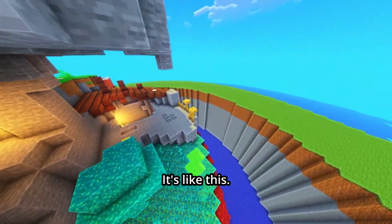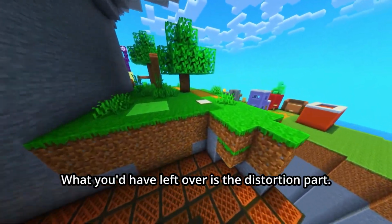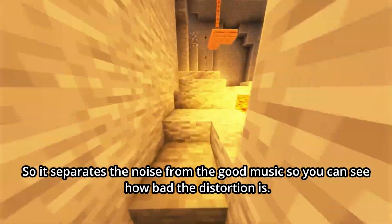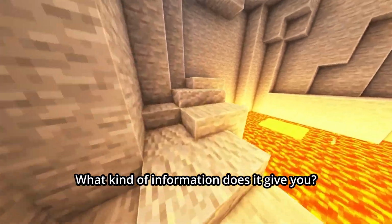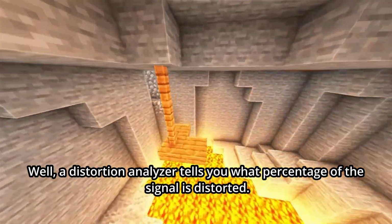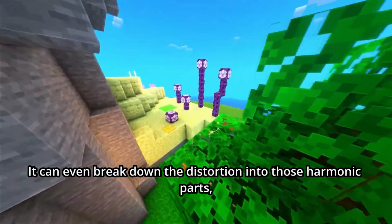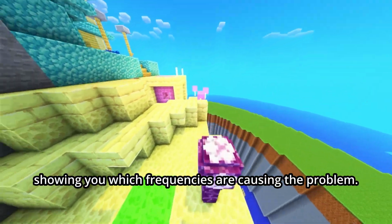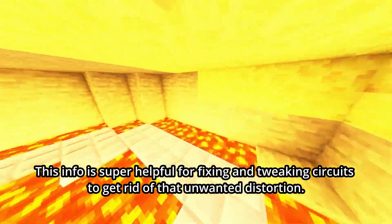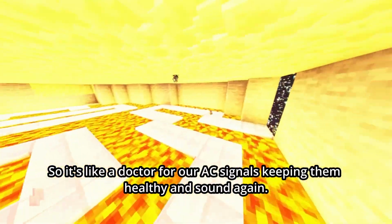It's like this. Imagine you could filter out the perfect main frequency of an AC signal. What you'd have left over is the distortion part. So it separates the noise from the good music so you can see how bad the distortion is. What kind of information does it give you? Well, a distortion analyzer tells you what percentage of the signal is distorted, so you know how pure it is. It can even break down the distortion into those harmonic parts, showing you which frequencies are causing the problem. This info is super helpful for fixing and tweaking circuits to get rid of that unwanted distortion. So it's like a doctor for our AC signals, keeping them healthy and sounding good. Exactly.